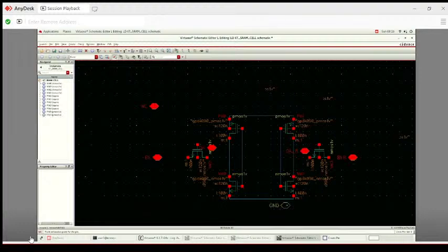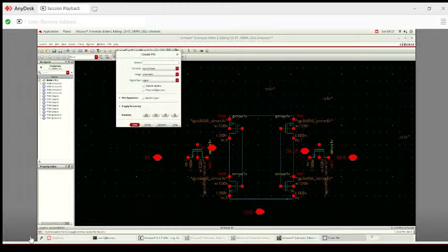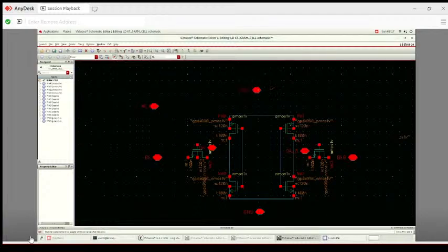Okay, so next the ground pin is placed, and here we are still missing one pin, which is VDD. So again we create pins, name the pin VDD and place it. We are placing it here, so all pins are placed. So let's give wire connections and complete the pins, complete the SRAM design.